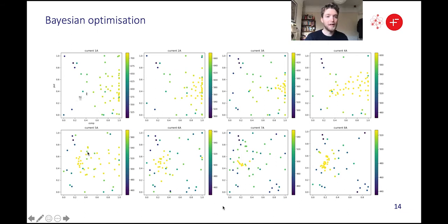You can see at low current, the optimal structure tends to be highly compressed. High compression gives us big accessible capacity, and that's because the simulation doesn't care so much about tortuosity because we're drawing current slowly. So there's time for those lithium ions to diffuse into the cathode and intercalate, even if most of the electrode is made up of solid active material. Whereas down at 8 amps, when we're trying to draw current really fast, we prefer an electrode made at lower compression, because we need that extra space so that lithium ions can diffuse into the electrode and intercalate into the material.